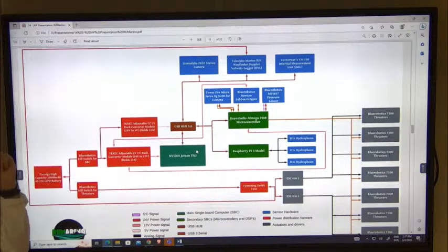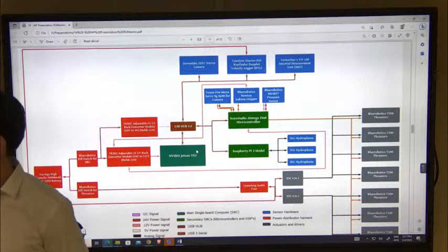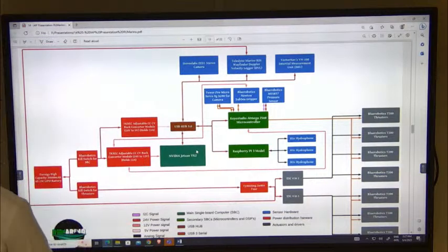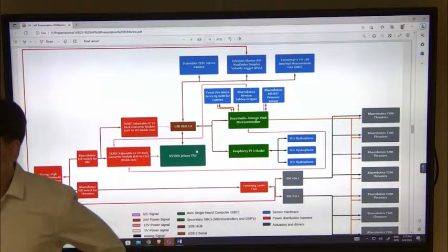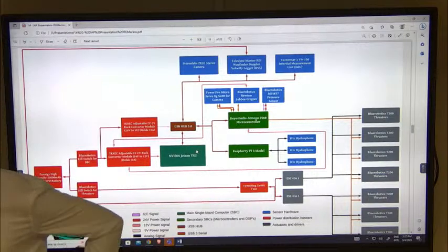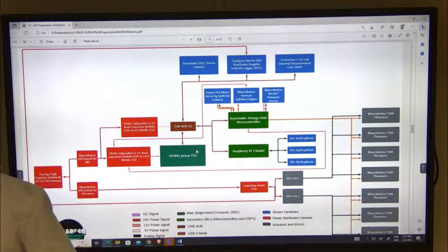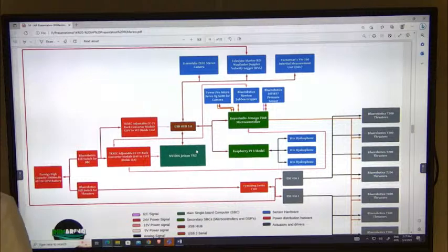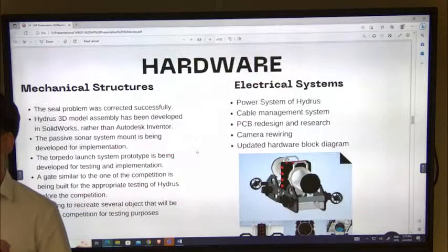In the 12-volt phase, we have the Jetson, the microcontroller, and the IMU. And then with the 5-volt, we have the camera and the Pi. So that's practically how our power systems are divided. So going a little bit back, and that's the updated block diagram.